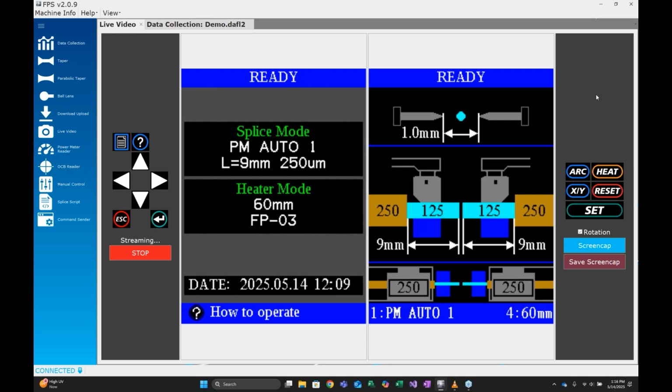Now, obviously, the optimization process is much more complex. But what this will do is give you the ability to handle some of the preliminary considerations before you dive into the details of things like arc power, arc time, stuffing, and all those other very important concerns, but those are more optimization related. What we're talking about is splicer capability and preliminary considerations such as rotation alignment, right? And we'll focus mostly on that because it's definitely the most complex and one of the most important, especially in the realm of things like multi-core fibers, for example.